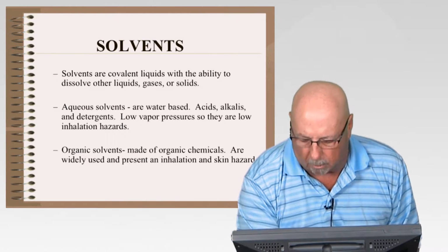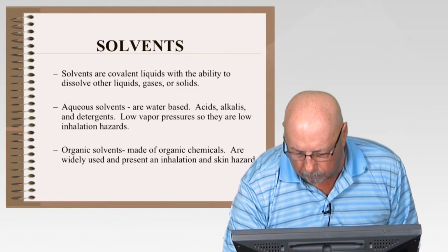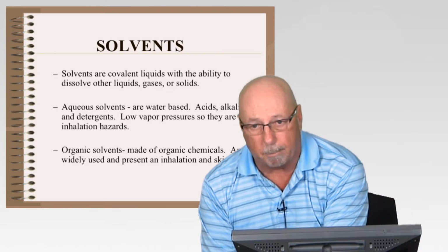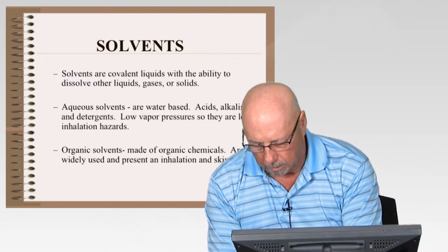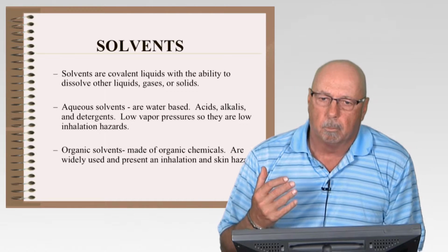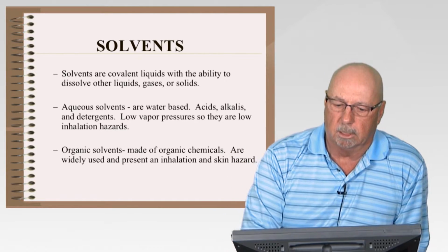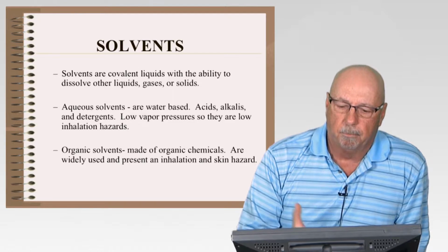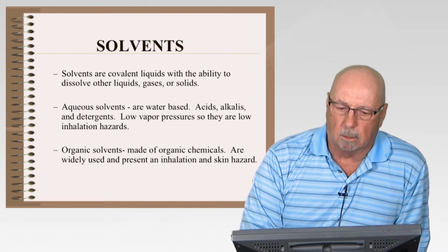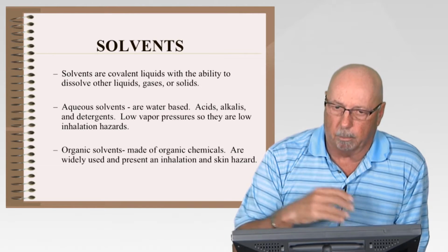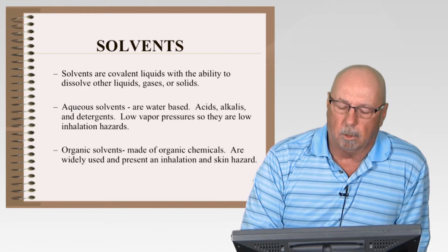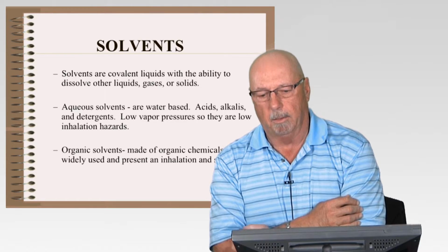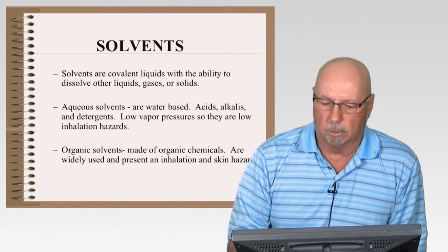But because of their organic makeup, you will find that organic solvents evaporate much more easily and therefore become more of an inhalation hazard to us. They can also be a skin hazard, but they evaporate easily, and as a result, they'll have higher vapor pressures, and they'll get into the air easier to where they become an inhalation problem to us.